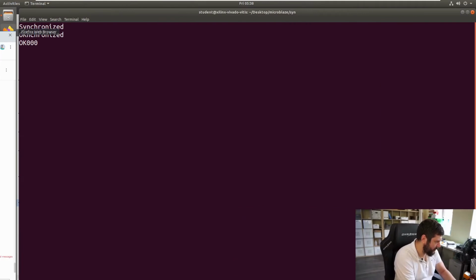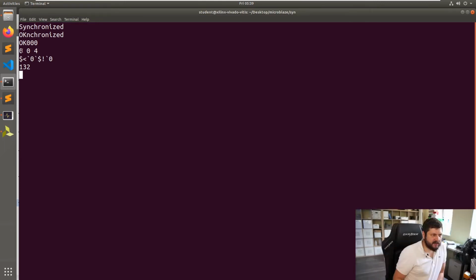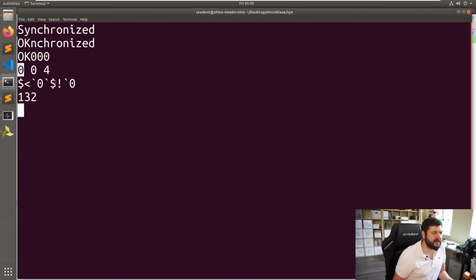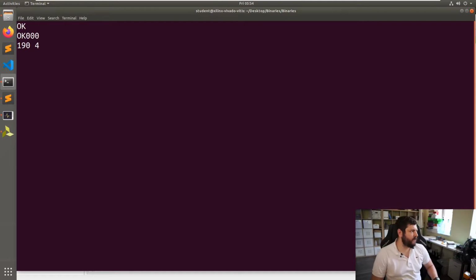For example, we can do R 0 4 as a command. This is the read command, and we're saying read address 0 and read 4 bytes. You'll get something like this. Right here, the R got overridden by a 0. What's the 0? The 0 happens to be a status code. It means command succeeded. I get the okay. Now let me do R 0 4 again. Wah wah, 19. We got a 19, guys.